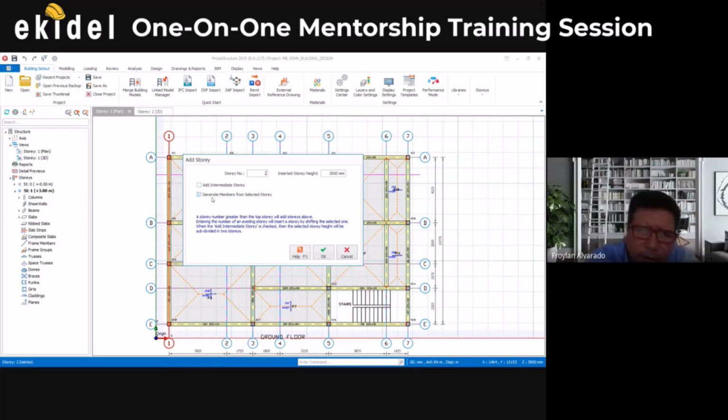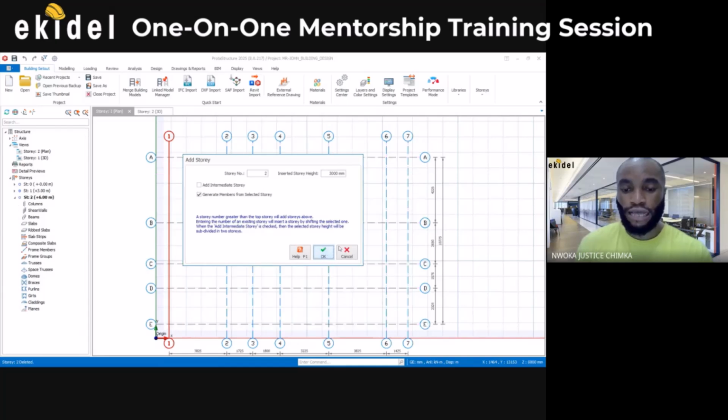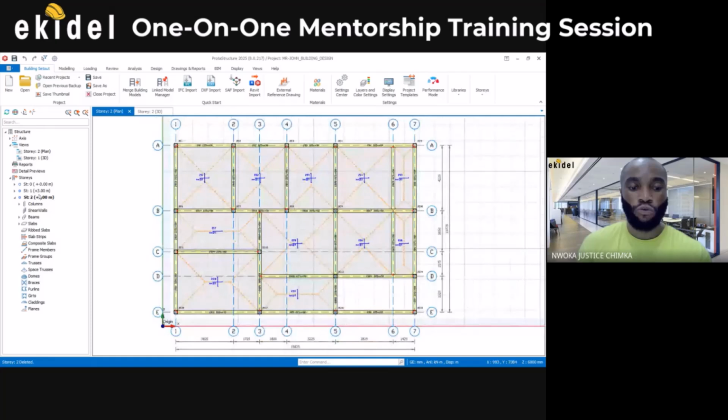Yes, now let me come here and put generate. It means that it will copy the slab, the beam, and the column to the next floor. Now, for this story height, still leave it as default. I'll show you how to change this later. Okay, then click on okay. So with this, you can see that we now have everything copied to this next floor. We have story 1 now, and then story 2.